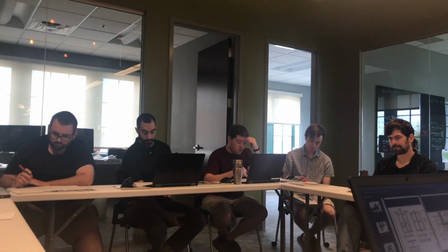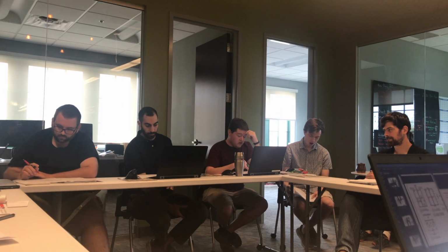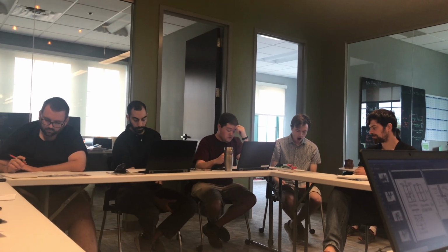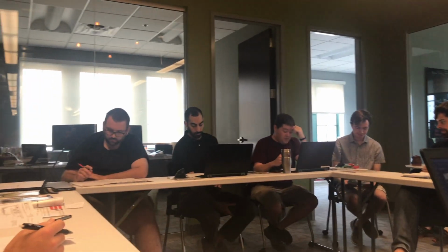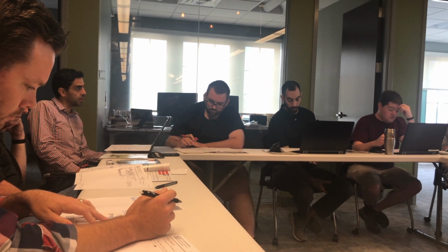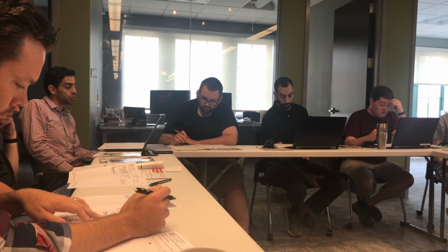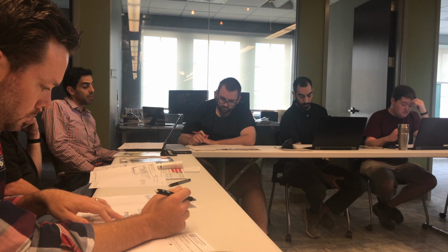Question about your recent model. At the screw head, did you fix a moment at that point? Is that why that curve goes to 0 right at the screw? No, I think I just added a constraint on the X for rotation, for stability. It wasn't just an X and Y constraint, but there's no restraint against moment on Z. But there wouldn't be any moment to the right of it.